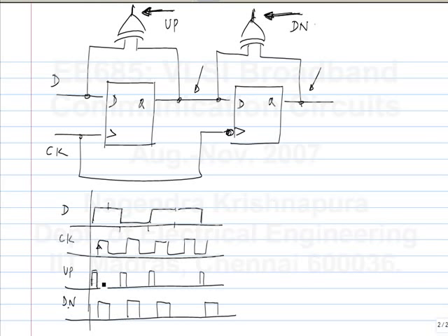When up and down are half period wide pulses, the average current is not 0. Maybe the average current is 0 when up is slightly more than half period and down is slightly less than half period. So the clock will align to something that is later than the midpoint of the data period. Okay. So the effect of mismatch in charge pump is basically a phase offset in steady state.